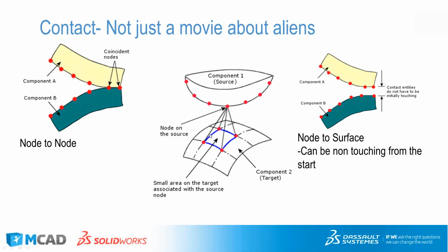So if you decide to make the surfaces the entire length as no penetration, you'll find that the solver is going to continually ask that entire length of nodes and elements whether they're in contact all the time. That's just wasted computational overhead that you don't need to spend while waiting for your solver to finish. It's important to note then that the node to surface can be a non-touching start, because on this it's calculating a distance. So for my previous example with the self-contact, we would use the node to surface because we want them to calculate that.